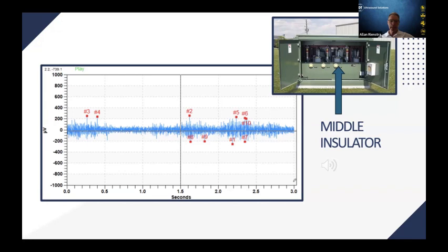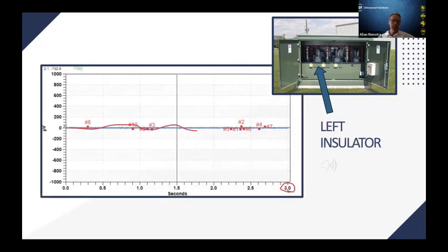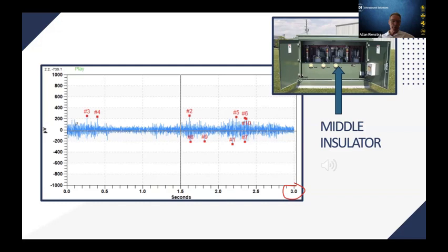Again, the same 3-second signal. If I go back, you'll see on the original signal, the microvolts, or the energy that we were picking up with our ultrasound sensor, was maybe about 50 microvolts. Now we're up around 100, 175 microvolts. And it got a little bit louder.